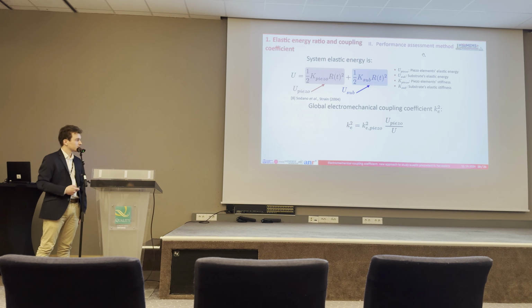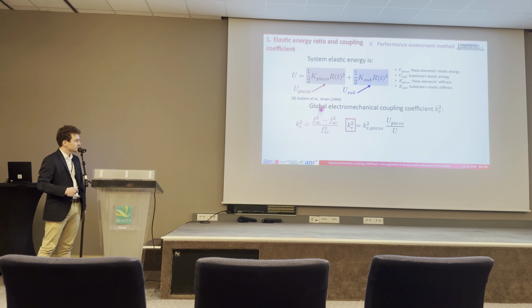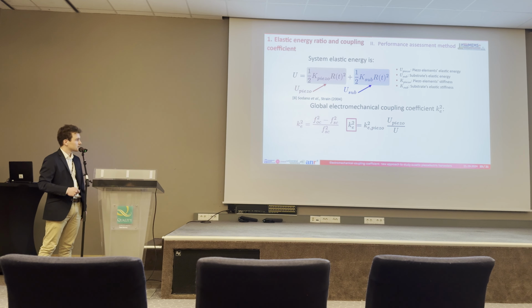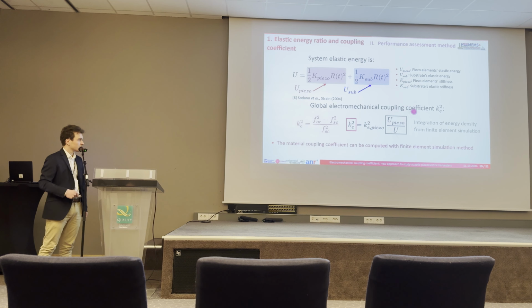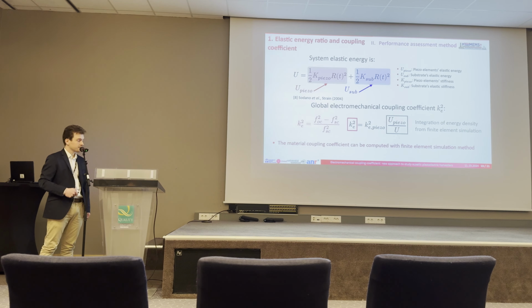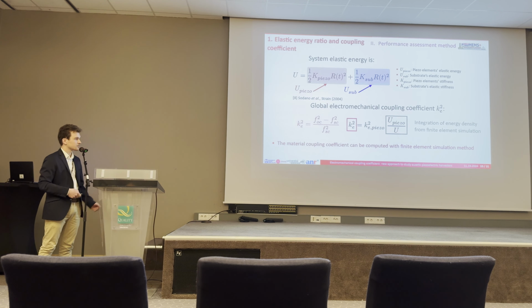So our method would be to get the global coupling coefficient with the resonant frequency on finite element simulation software, and also the energy ratio on the software, so we can get information on the material coupling coefficient.